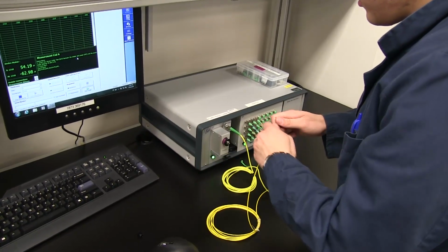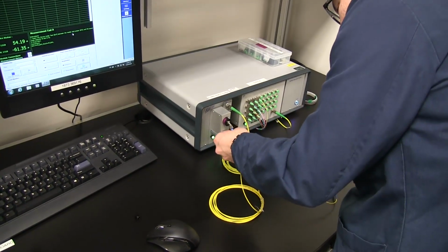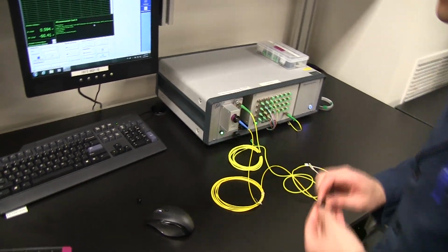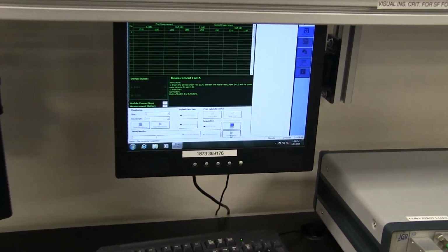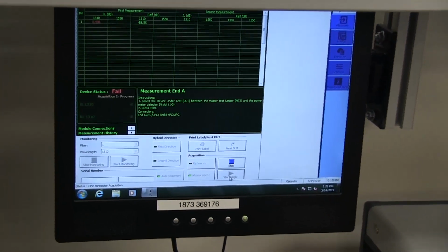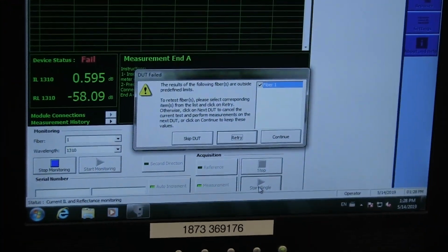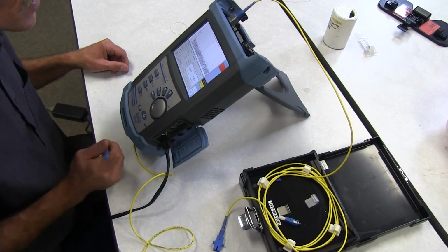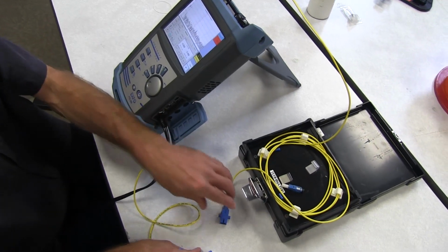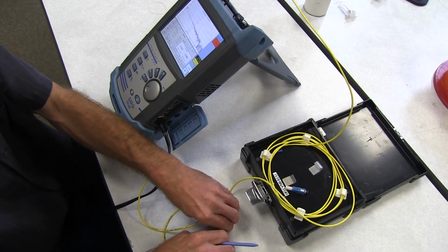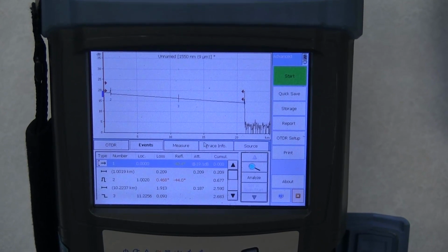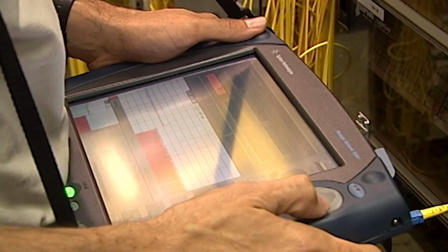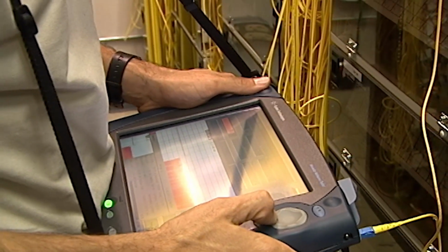The insertion loss and reflection meter is an ideal instrument for measuring the insertion loss in a fiber span bidirectionally, as well as the reflectance of the terminations. Although it does measure the magnitude of reflections, it does not provide information as to the cause of the reflections. The optical time domain reflectometer is an instrument used to test the light transmission ability of an optical fiber cable or span and is the only instrument that can determine both the location and magnitude of a problem. It can determine the length of a fiber, distance to events, total end-to-end loss, as well as the attenuation and reflectivity of discrete components along the fiber.